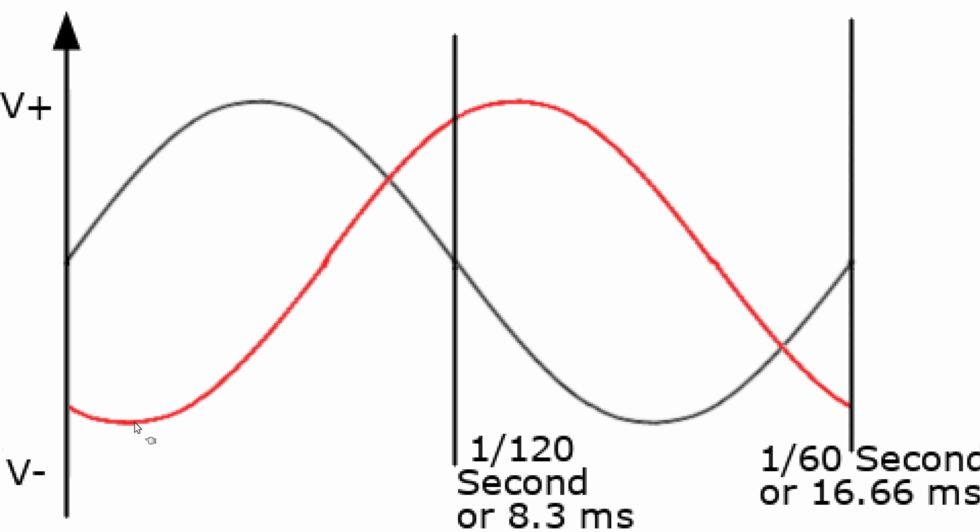Here, the distance from there to there is greater than back here. And you'd see, if you're looking at this with a ruler, they'd be getting further and further apart until we reach somewhere right in here where this one's approaching its hump and this one is leaving its hump. At that point, the phases actually start coming closer and closer together. Now, again, this is voltages. The wires themselves are not actually moving, but the voltage potential is getting closer and closer to each other until they cross right here, and there's zero voltage difference between the two wires.